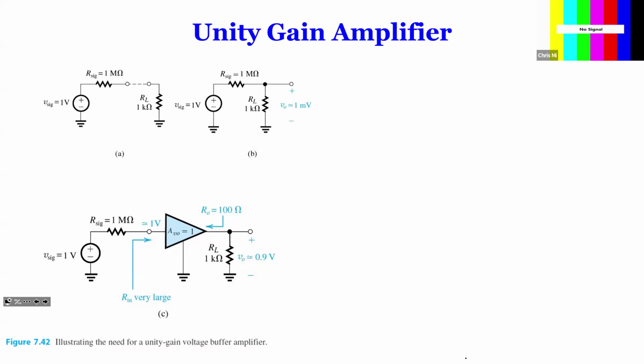So if I want to ask you a simple question for circuit A over here: you want to increase the percentage of voltage that gets amplified. What would you do? What are the things that you can do in this case? Well, suppose those resistances can be changed. Make our internal resistance as small as possible, or our signal resistance as low as possible.